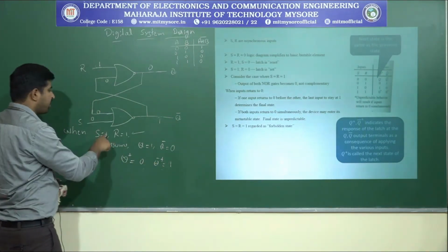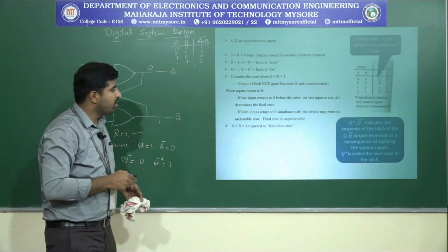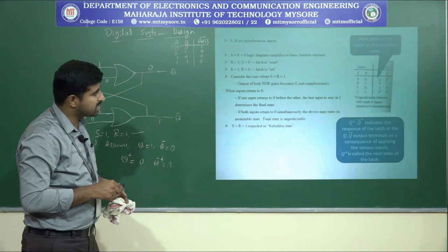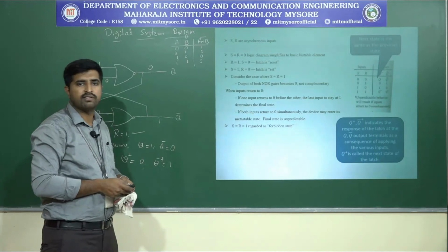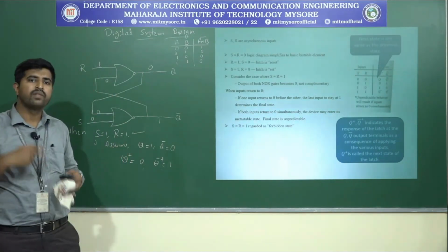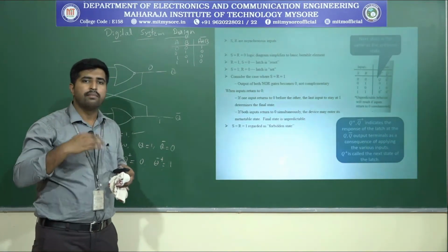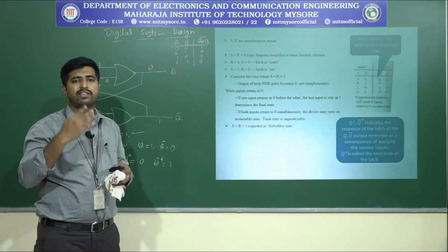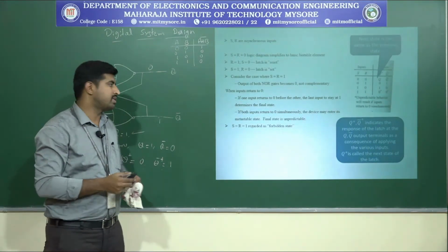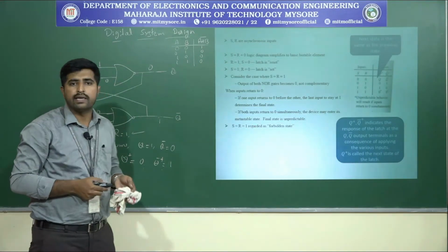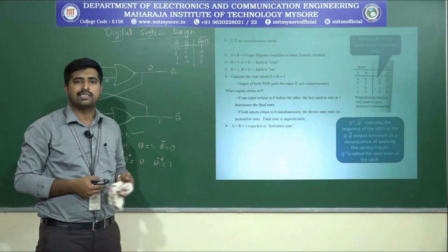But if S and R both become 0 simultaneously, the device may enter its metastable state. We discussed the metastable state already, where the output is not defined. It lies between logic 0 and logic 1, so the final state is unpredictable. We need to avoid this state when using the SR latch.